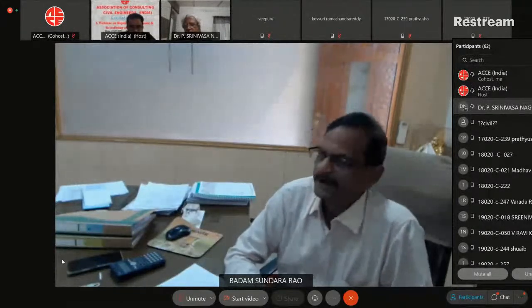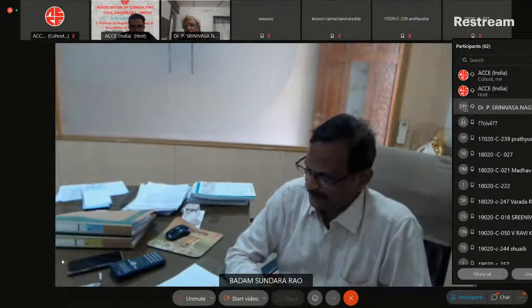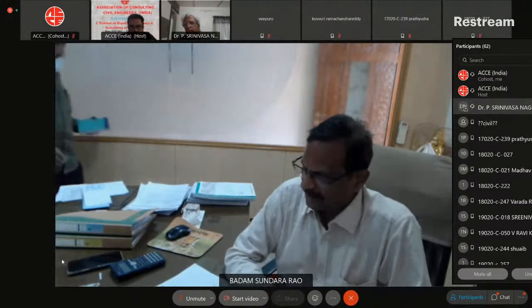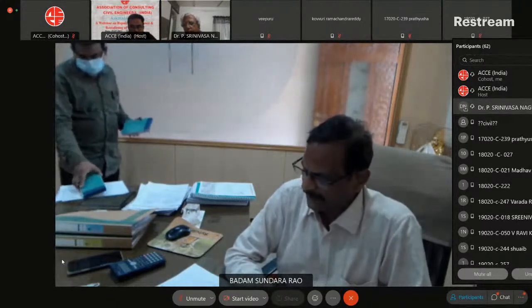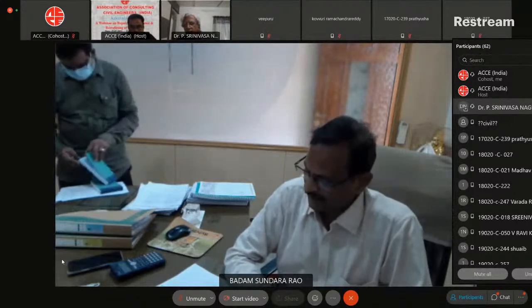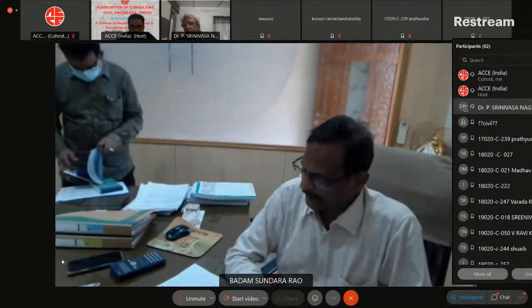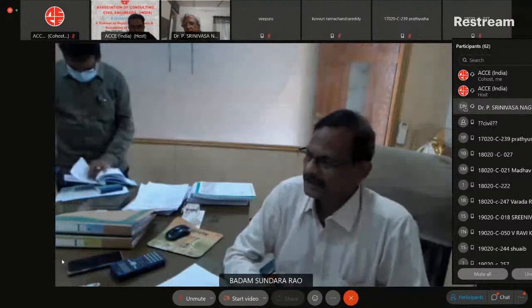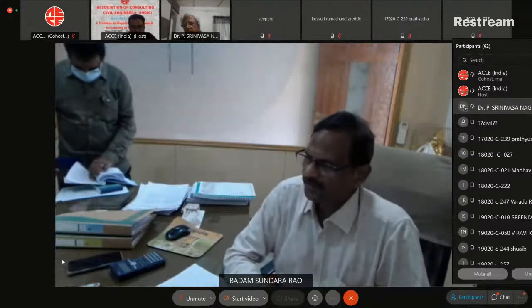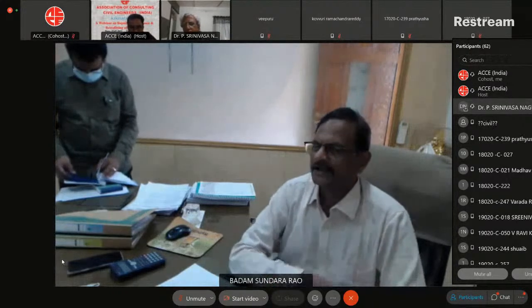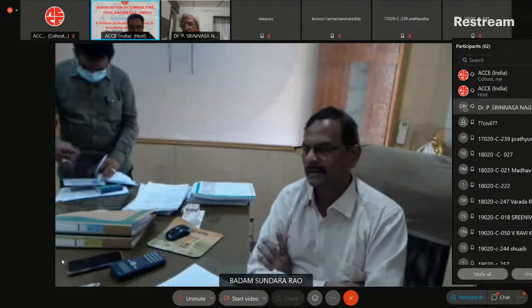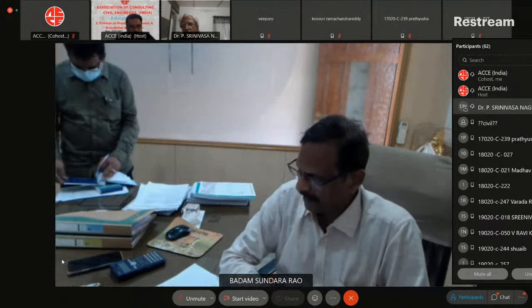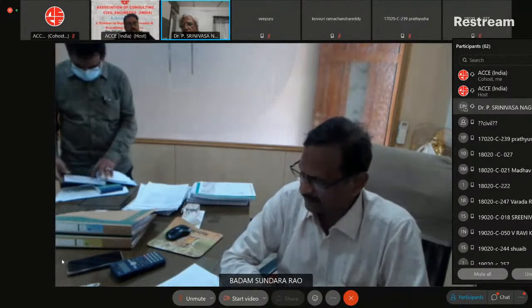And proper mixing is important. Quality of mixing is very important. And one more aspect people mostly neglect now is the quality of curing. Curing is very, very important, and it is to be done for the prescribed period. And periodical inspection and maintenance is very much required, and it is to be attended to immediately. A small repair, if not attended to, may lead to major damage or sometimes even catastrophic failures. To avoid that, proper annual or periodical inspection and proper maintenance are very much required.